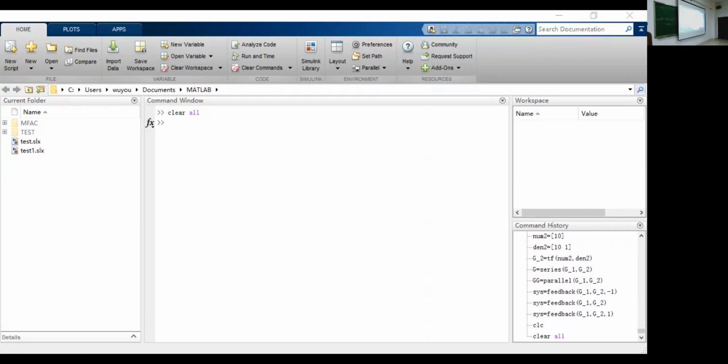For example, in this transfer function block, if we put four numbers in the denominator, Matlab automatically will put that on. If it is four numbers here, you apply it and it just shows the same. It's just the denominator coefficient matrix according to the decreasing order of s. Clear?